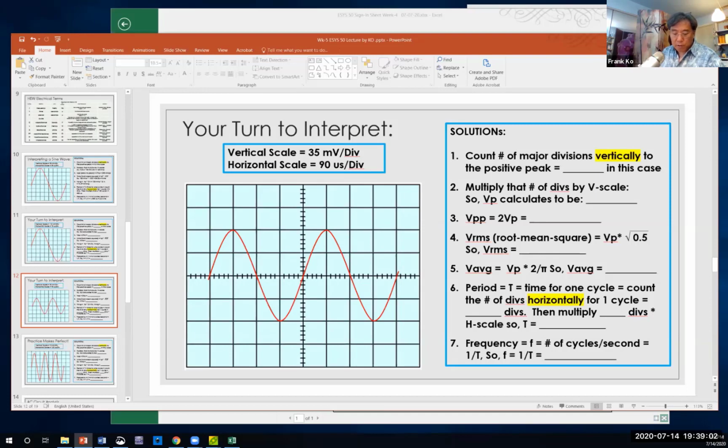So it simply is an indicator that lets us know what on the display we don't want to exceed. The most useful values to us are really going to be the volts peak and the VRMS and the period and frequency. Those are the 4 most important quantities. The rest is academic interest.